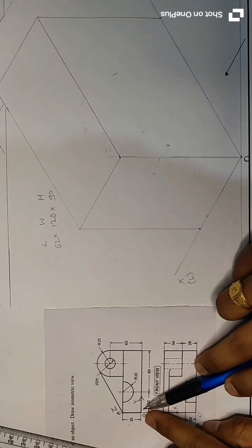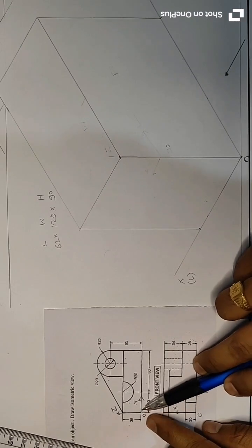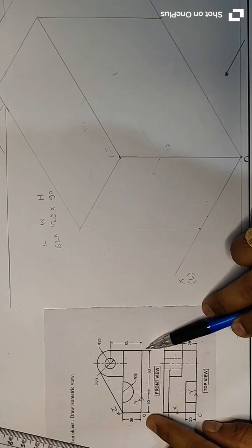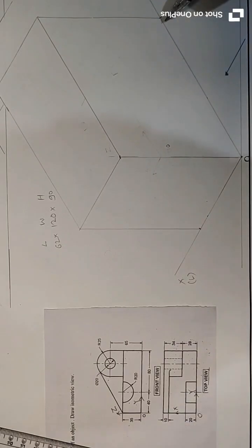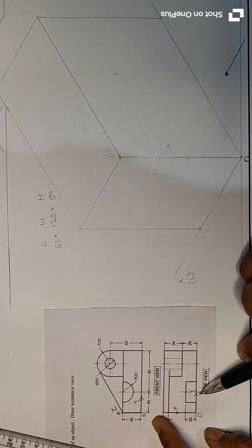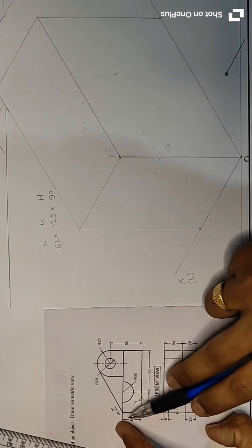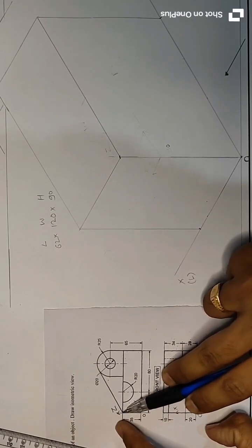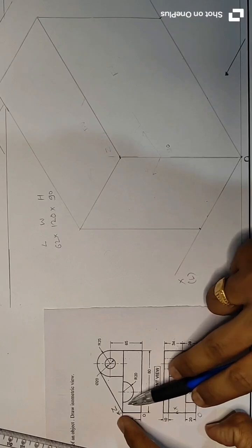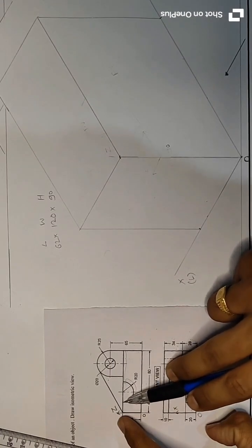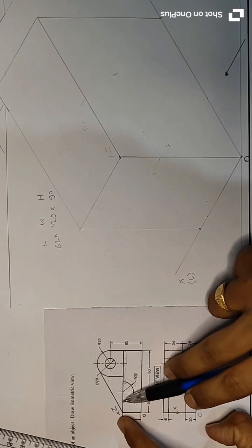Now see, in the front view, from point O along the y direction, this is a regular line of 120 mm. So we can draw this line dark. At a height of 35, that is z equal to 35, there is a line, then a semicircle, and again a line. Above the semicircle there is again a regular line.